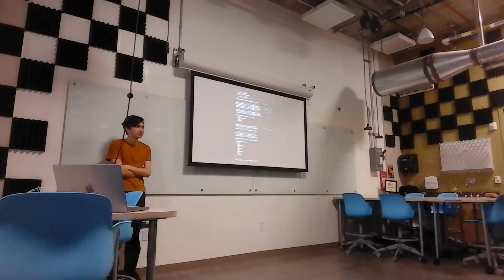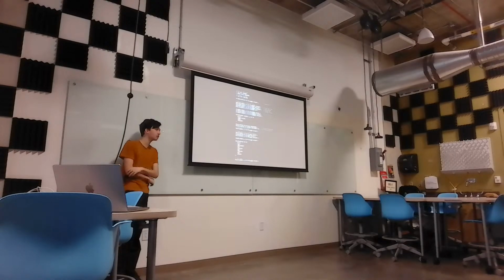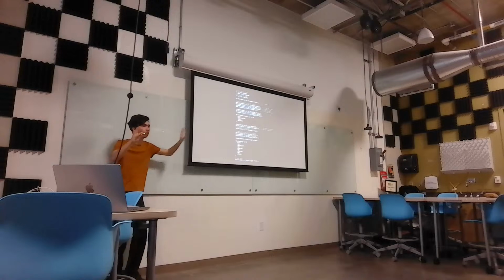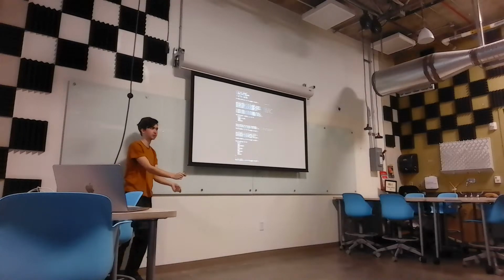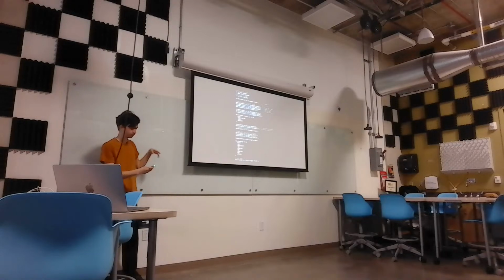How does Rust, being a programming language, know how to control peripherals? Rust has no idea what a peripheral is. Well, some very smart people made a tool that parses the manufacturer's specifications of microcontrollers into Rust. It's called a peripheral access crate. A crate in Rust is like a library or a package. It automatically says, okay, we know this region of memory, if you put a bit here, it does this thing in this peripheral.